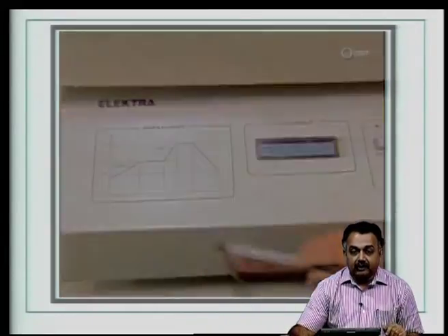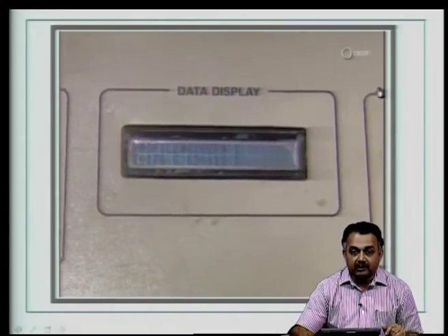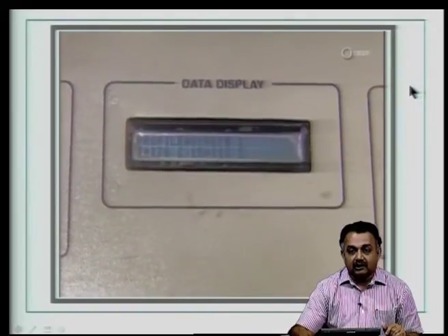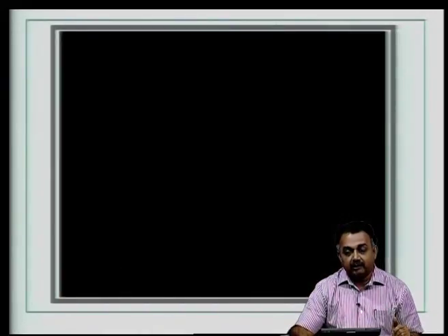And also you can expect to some extent a very good self alignment, but for BGAs you will see later in this chapter how self alignment becomes very important when you mount BGAs, because BGAs, the solder balls, you cannot really view from the top. At least in this case for surface mount devices, the pins are outside the package outline, and you can have a look at the soldering process and look at the defects.